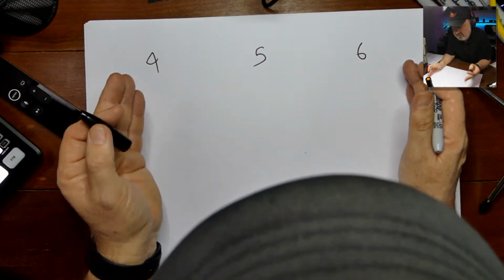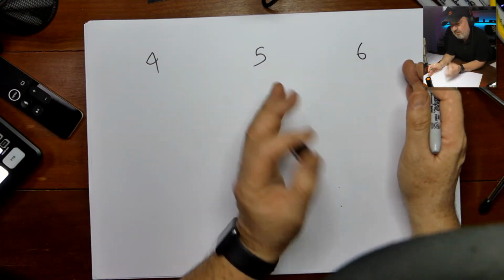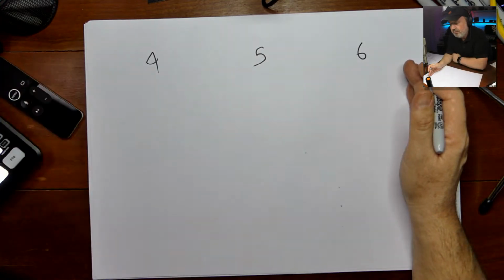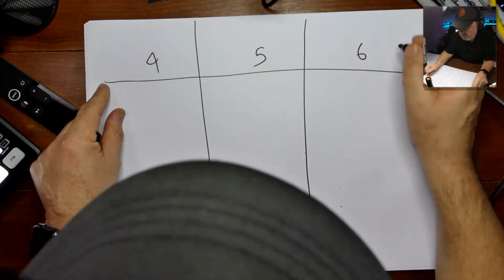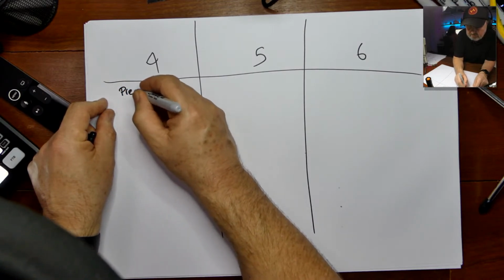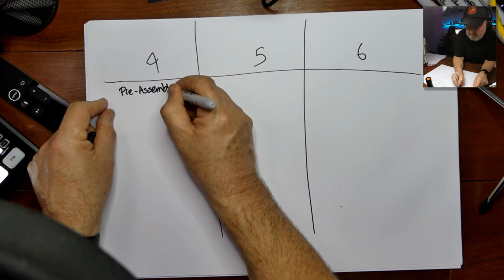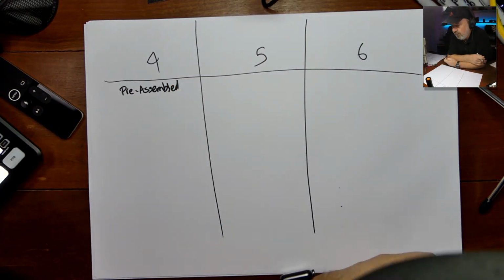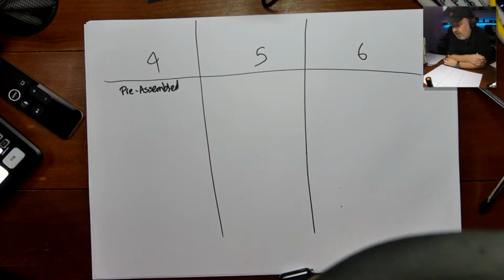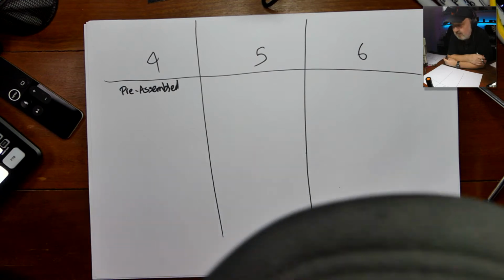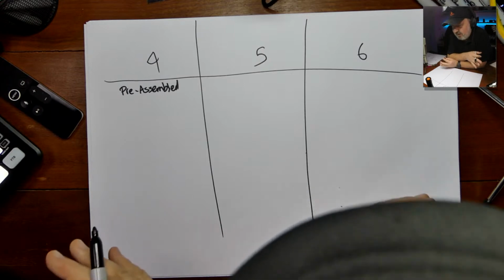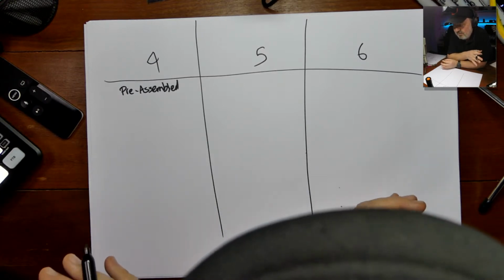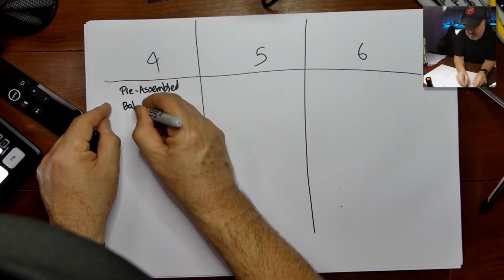So it's a bit repetitive. If you read section 4 and then section 5, it's almost the same with just a few minor differences, because we didn't want you jumping all around the standard to comply. Section 4 is for pre-assembled battery energy storage systems. Pre-assembled basically means there's no on-site manufacture. All of the components are supplied, a bit like an IKEA table, but you don't have to go to the hardware store for your own screws. You can't make up any cables or select any lugs; everything must be part of that system. It is also tested to various standards.